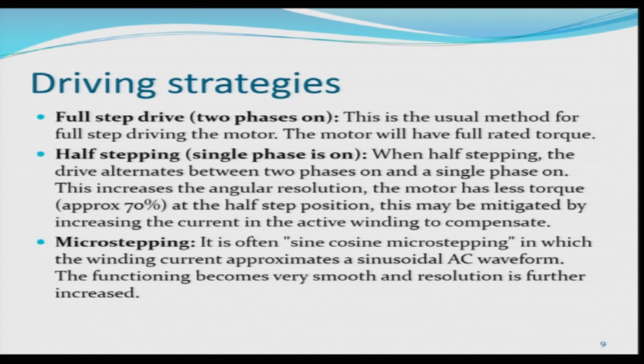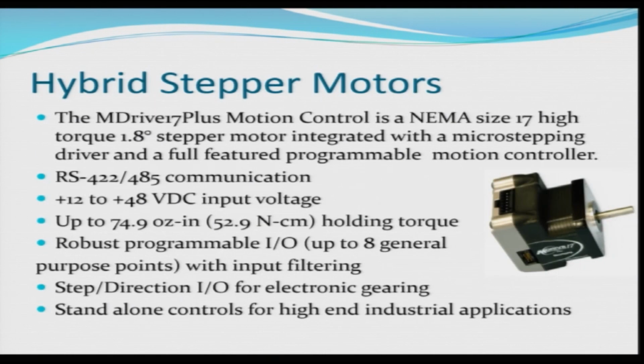There is another driving strategy that is called micro stepping. It is often sine cosine micro stepping, in which the winding current approximates a sinusoidal AC waveform. The functioning becomes very smooth and resolution is further increased.